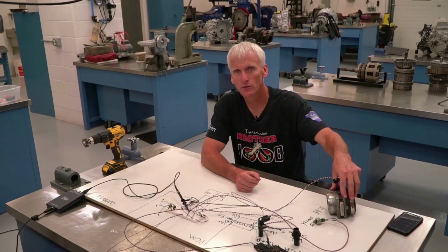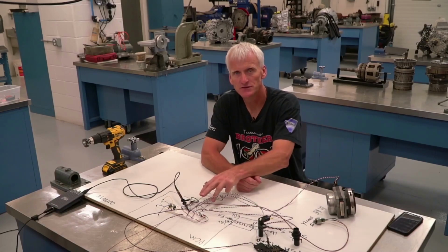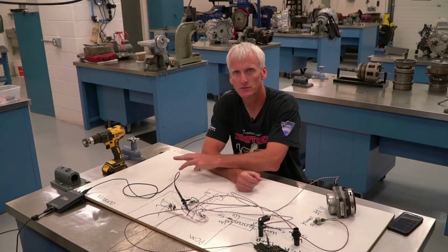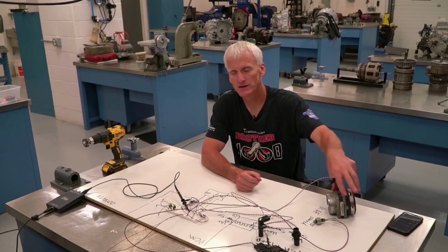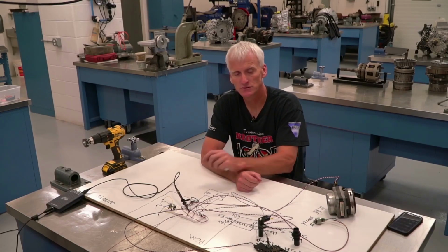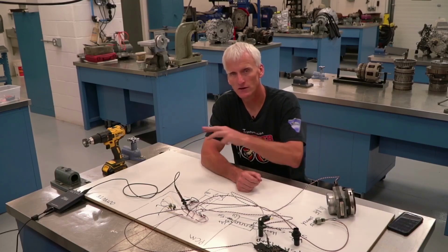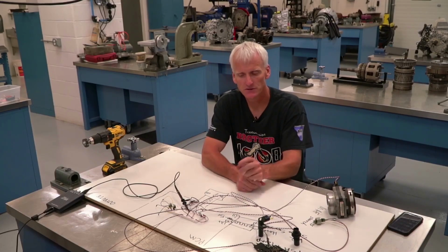Obviously, that's an extremely important sensor. The computer is going to use that information to determine how much pressure to apply these clutches with so they don't slip. So if this is feeding false information, we could have transmission issues. So this engine component could cause transmission failures. So those are all inputs.